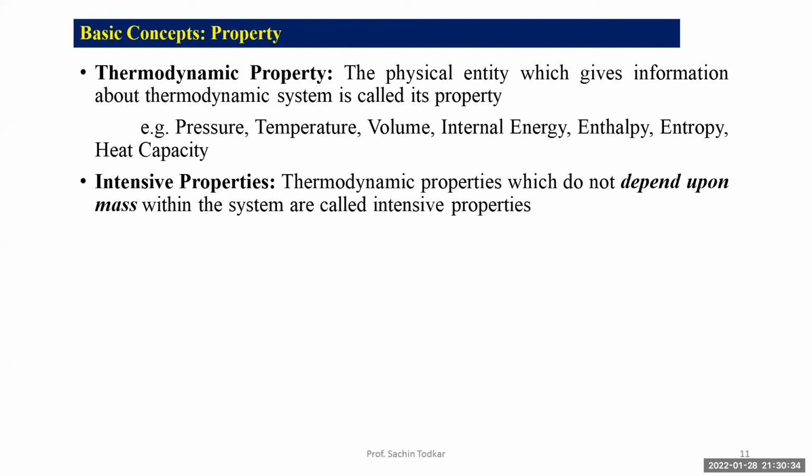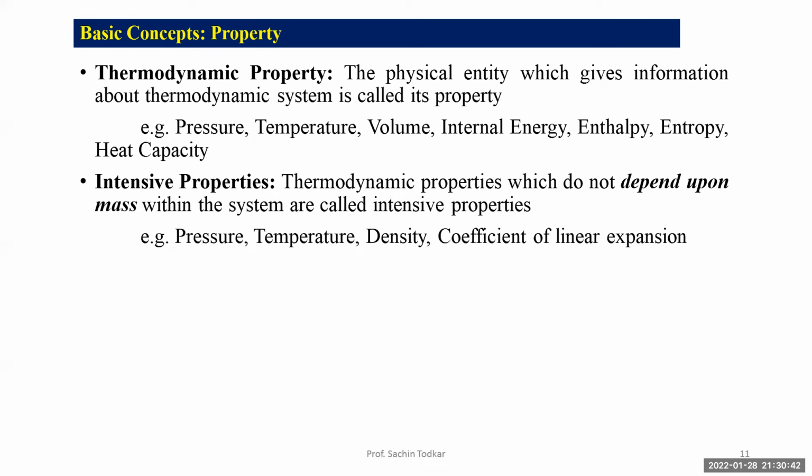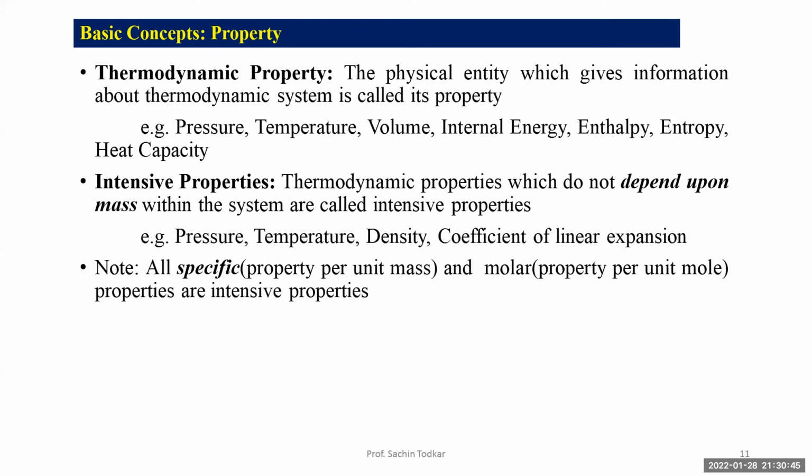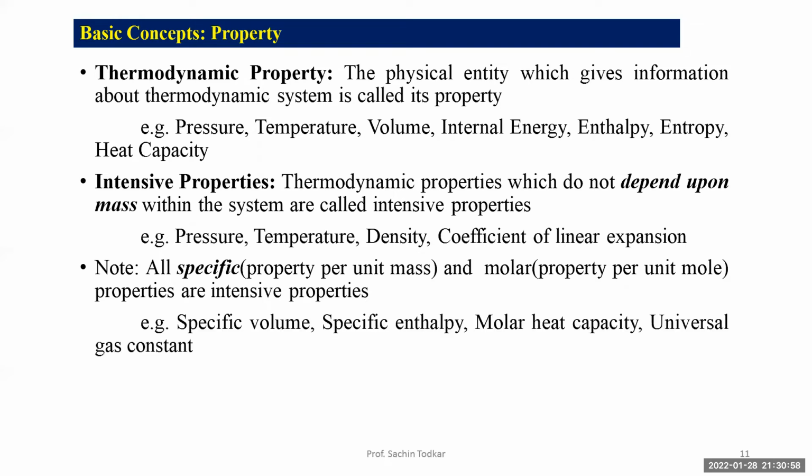Intensive properties are the thermodynamic properties which do not depend upon mass within the system. Examples are pressure, temperature, density, coefficient of linear expansion. All specific properties, that is property per unit mass, and molar properties, that is property per unit mole, are intensive properties. The examples are specific volume, specific enthalpy, molar heat capacity, universal gas constant, because they are per unit mass or per unit mole, so they do not depend on mass.